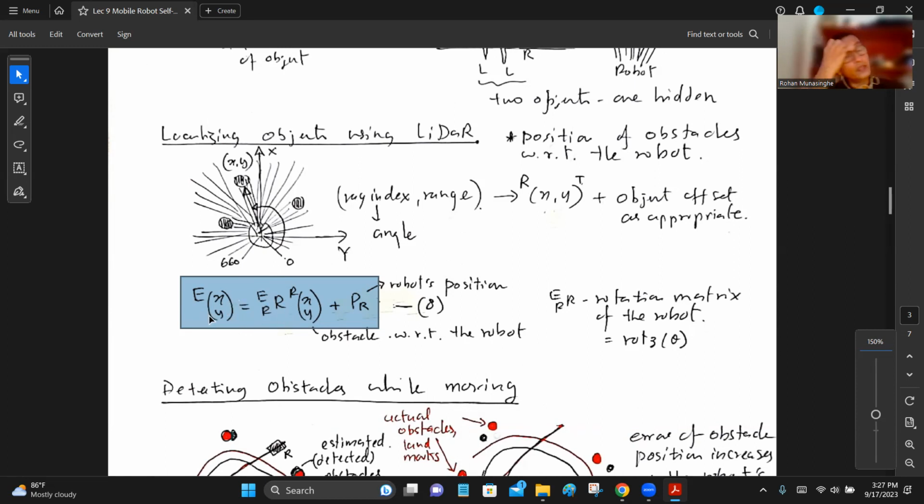This means when the robot takes a LiDAR scan around it, the moment it understands there are n number of obstacles, or landmarks, around me, and they are located at these angles with respect to my coordinate frame, and at these distances. Now you have this equation number 8 to calculate the positions with respect to the world coordinate frame, and then plot them on the world map. There are obstacles in these locations. Now it's not with respect to the LiDAR or the robot, it's the world coordinate frame.